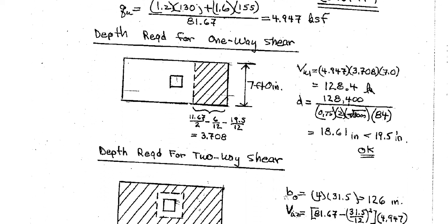So first, now we will do one-way shear. We know one-way shear is critical at d distance from the face of this column. So this is my column, at the distance from here. Last time when we did square footing or wall footing, we assumed a 1 foot strip.